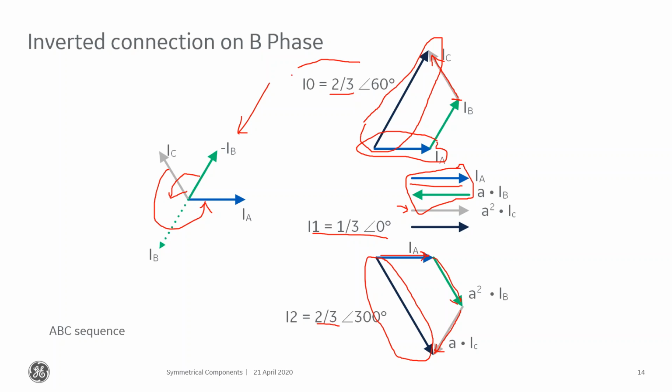So anytime, and the reason I say this, and we'll talk about this in a few moments when we talk about the way the fault sequence networks interact, it is really impossible for my negative and 0 sequence quantities to be greater than my positive sequence quantities. And if I see my negative and 0 sequence quantities larger than my positive sequence quantities, that is a wiring error.